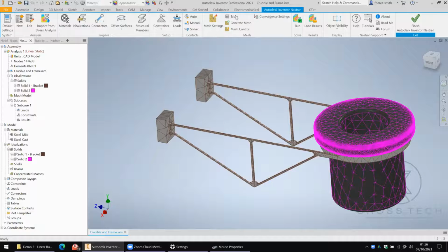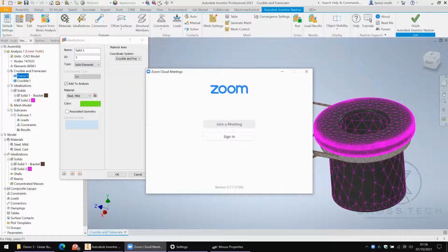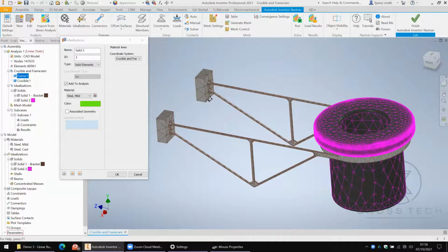For the chart, when the eigenvalue is above 1, does it mean that the model will not buckle? Yes, that's right. So in a buckling analysis, if the absolute value of the eigenvalue is above 1, it won't buckle. That is to say, if you get, say, -3, it's still in absolute terms above 1, and therefore you're okay. If you get an eigenvalue of, say, 0.7, then it's going to buckle, and you have to worry. Okay. All right. So those were solid idealizations.